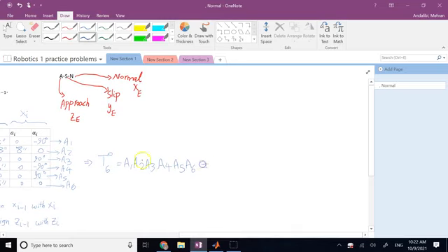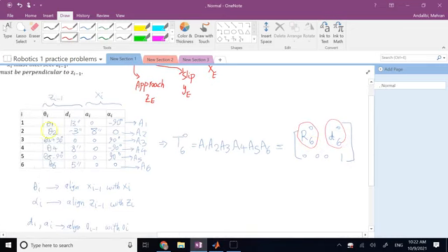And this is going to be a 4x4 matrix, which has a rotation matrix in it, R of 6 with respect to 0, the origin of 6 with respect to 0, 3 zeros, and a 1. And the goal of forward kinematics is to find these guys. If I give you the 6 values of what? Theta 1, 2, 3, 4, 5, and 6. In many DH tables, you probably see a star next to the thetas to tell you that these are the joint variables. And the rest of the parameters in each row are just constants.